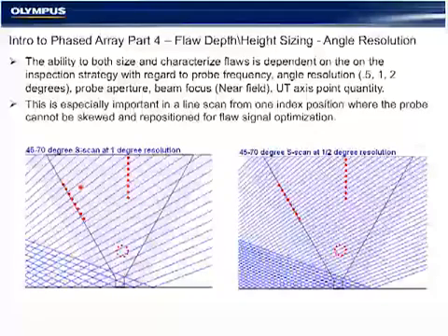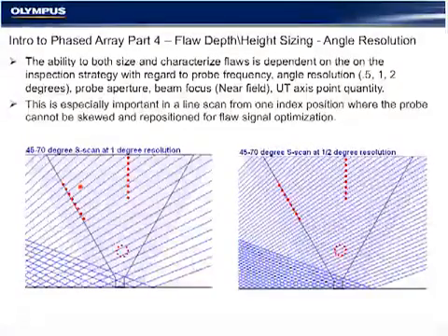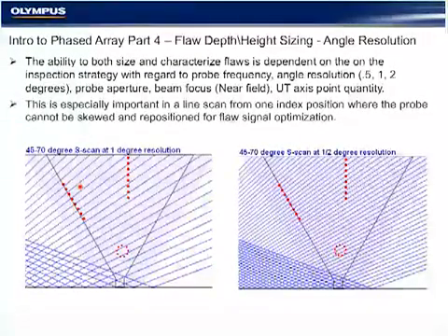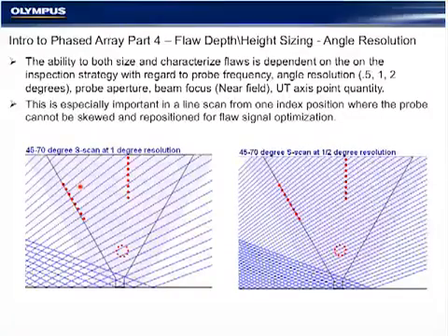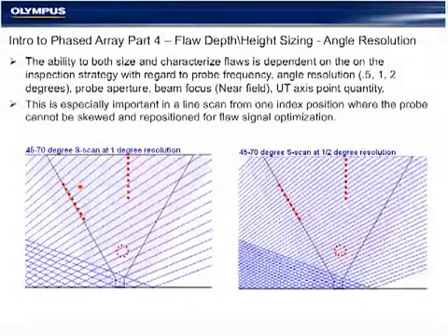In both cases, for our typical welds, they would provide 1 millimeter sizing accuracy, which is often a common benchmark for what people would expect paying for phased array inspections. With the use of TOF, that can be improved. For the type of material, carbon steel, we would expect 1 millimeter accuracy for length and depth height sizing if we had a good plan and a good calibration strategy. The thicker the material gets, the more accurate that becomes.